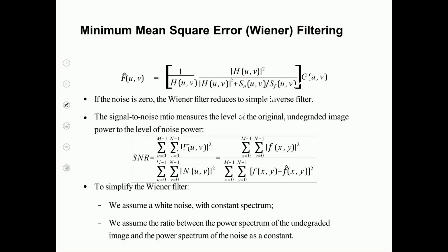To put in this equation, we'll get that. Okay. And now let's say you are applying the filters. So how to quantitatively find that your filter is improving the results? In this equation, let's say any filter like inverse filter or Wiener filter or any other filter, when you're applying, one of the things that I need to check is the SNR.